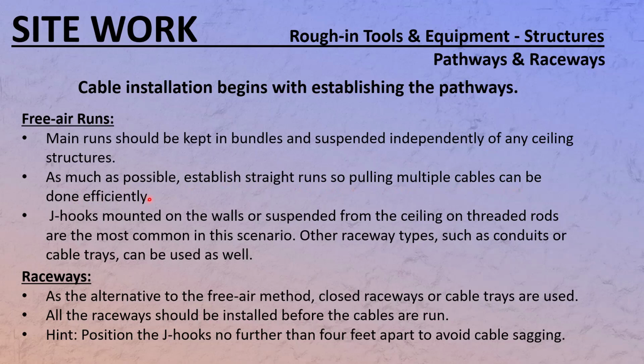But if you can, pull the whole bundle in a straight line, that's a bonus, because you can pull more wires in a shorter time. If you have 2 or 3 wires to pull, there's no difference. But if you have 800 of those to pull, the little bit of time it saves you accumulates.